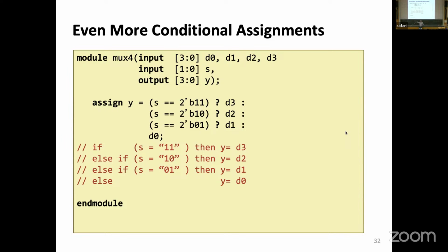So this is one of those things. There is no if-else in normal combinational statements. They don't exist. You already hate the language. Well, it's even worse. If-else, case, and those things exist in another context. We will come to it next week, okay? It makes it much more complicated, but for right now, just know they don't exist. If I want to use this kind of statement, this is what I'm doing. And by the way, this is just combinational circuits, right? I'm assigning things to each other. I am saying Y is going to be this multiplexer structure, and we'll select one of those 4 bits.